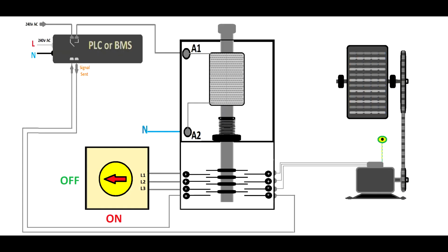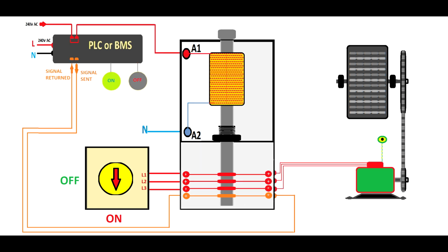Actually I have some other videos where you can see how this is working, but you can see even in this video you have a power circuit at the bottom, but the power circuit will never reach the motor until the PLC on the left hand side top closes the contact, and then the contactor solenoid will be enabled. It will create an electromagnetic force which will drive a pin down, and it will close the circuit. Then the motor will be enabled and will turn the fan.